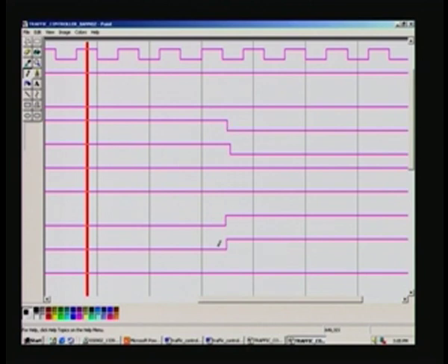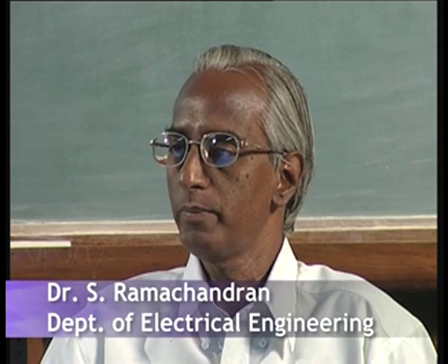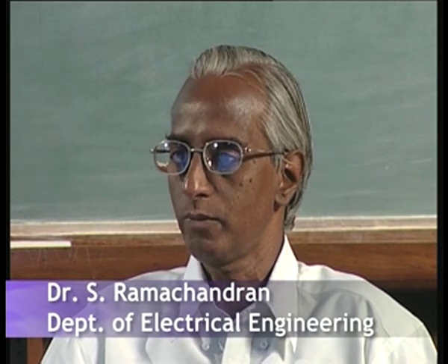So, you can't really predict how much delay will be in each of these signals, because it has to come through several gates, and those gate delays get reflected as you would see finally when you put it on the FPGA board and make it work. Although this is a simulated signal, it is back annotated with the gate delays, and that is how it is working here.